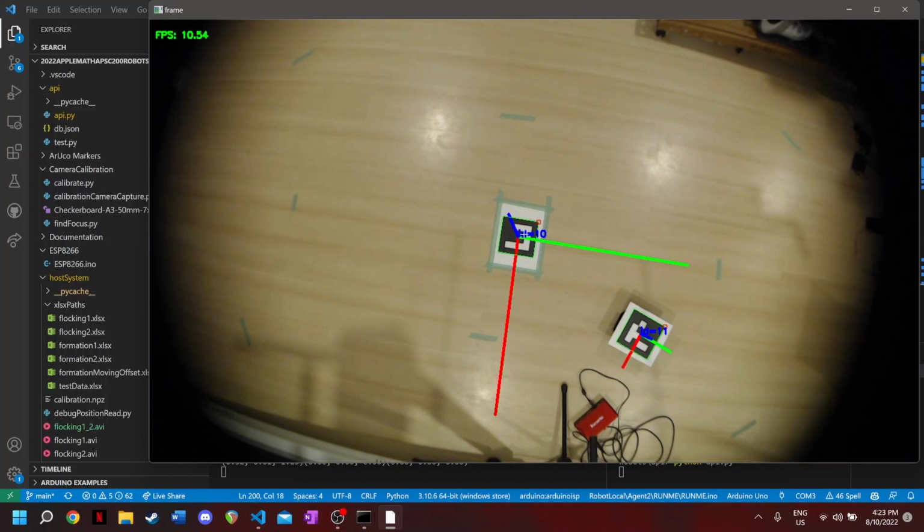Now it's time to turn on the robot. Now the robot's going to wait a couple seconds so that the ESP powers up first. And then it's going to try to move to its first position. Then it's going to execute the path. This path just has to go in a straight line. Okay, it's done. It's going to wait. I think the timer on it until it starts doing anything again is 8 minutes. So you got plenty of time if you just want to leave it on.